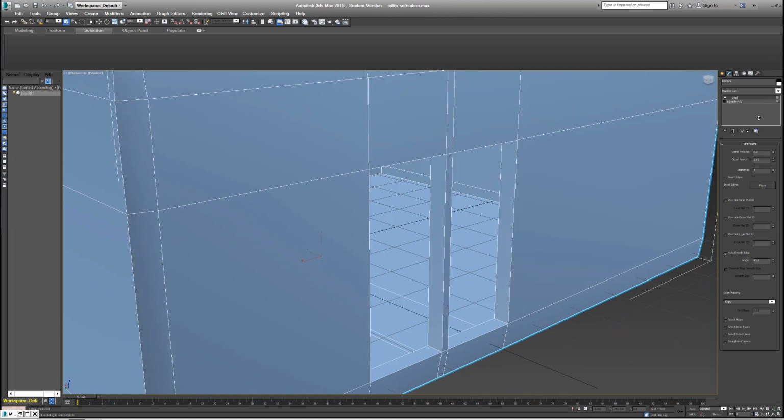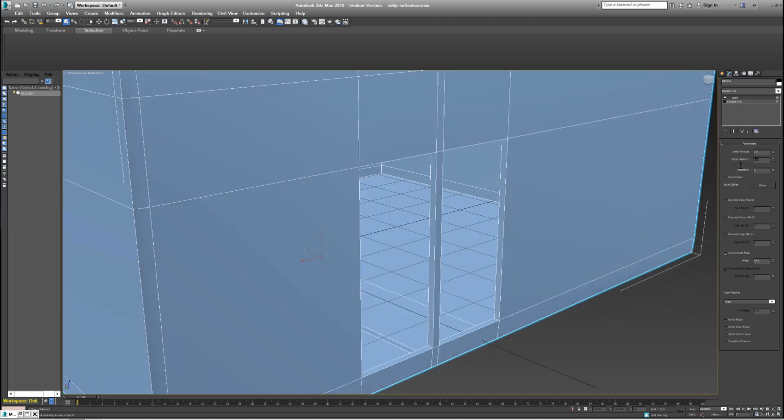It's sort of as though you're creating a balloon around your model, and it's giving it some sort of depth so that when we render through the model, it's looking more realistic. It's going to cast more natural light, more natural shadows. So let's go back, and we'll just say I can type in an outer amount of 1. If I control the inner amount, just to give you an idea of what it'll do, it'll actually push the walls inside the space. Too much and you get these sort of glitchy planes coming in and out. For now, I'm just going to keep my inner amount at 0.